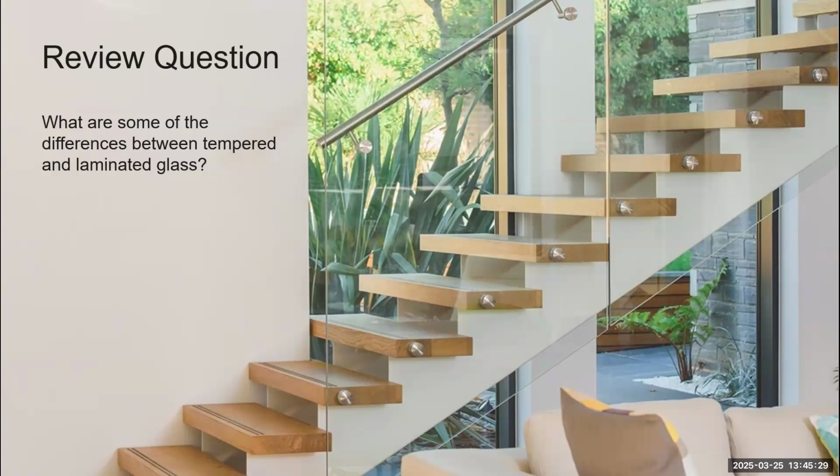How do you deal with roof element if using fascia mount on the parapet wall? So the answer is, when we put a base shoe, either fascia or top mount, onto a parapet wall, we will have a wind velocity factor that we will have to increase under ASCE, because there are multiple factors we have to take into play.